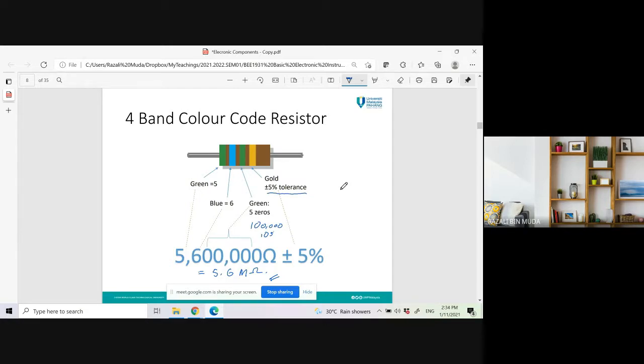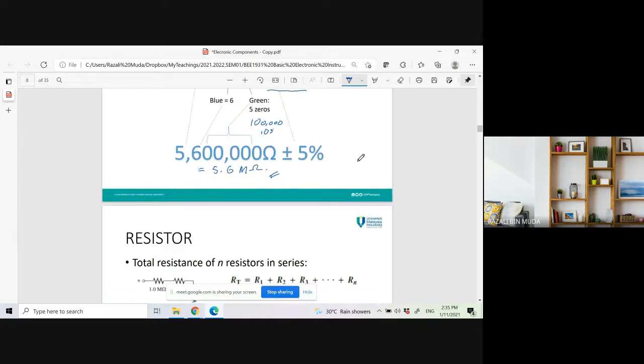You need to remember, if you measuring the resistor, you need to disconnect the resistor from any voltage source or any current source. You just measure the resistor on its own without connecting to any power source. Okay, in the lab we will discuss that later lah.